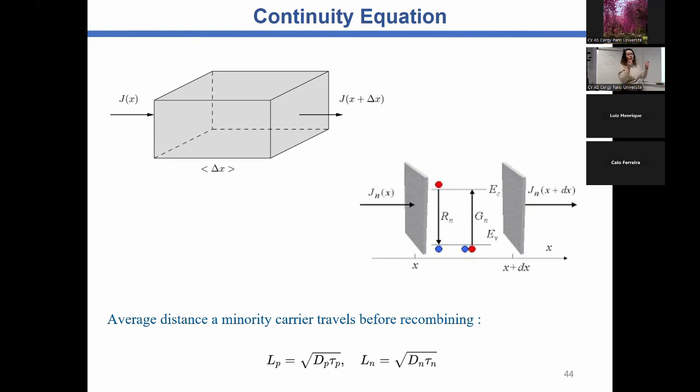So if you are in the lab and you want to know if there is any continuity in your material, we just grab the multimeter and put it on the continuity setting.